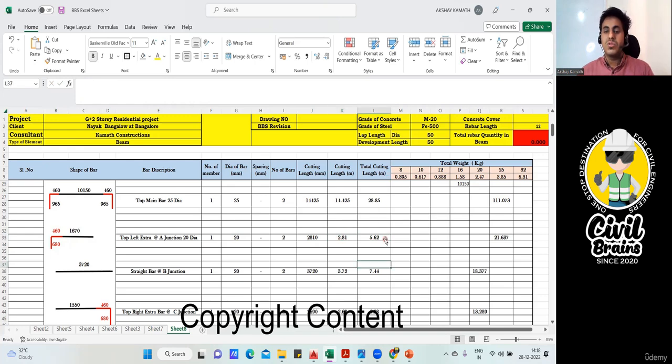The total cutting length will be 2.81 multiplied by 2 and multiplied by 1, which gives 5.62 meter. It's the total cutting length of my top left extra of 20 dia, 2 number. Once I got the total cutting length for a 20 diameter bar, the weight will be how much? 5.62, it's a 20 diameter.